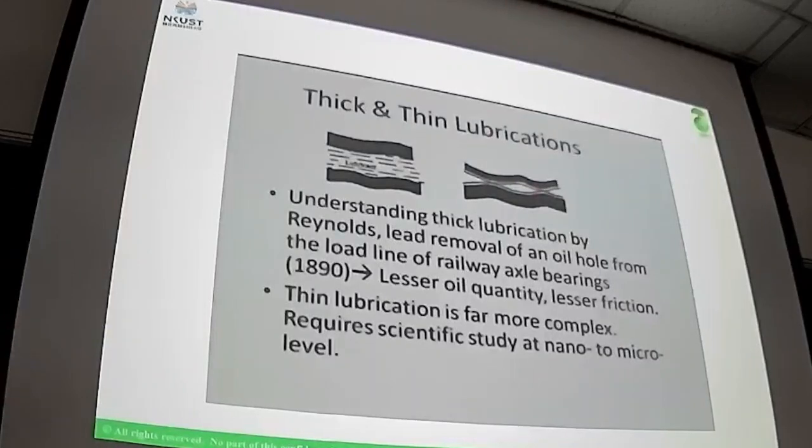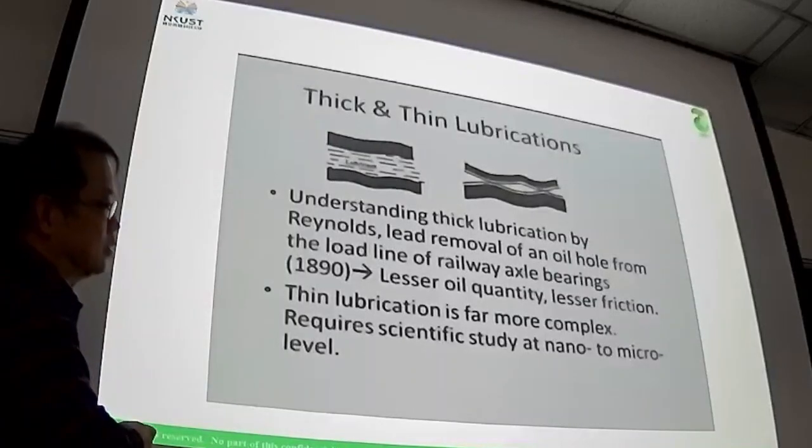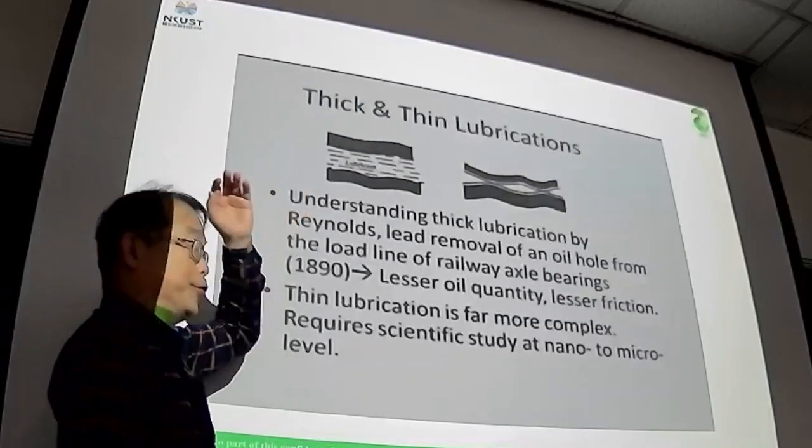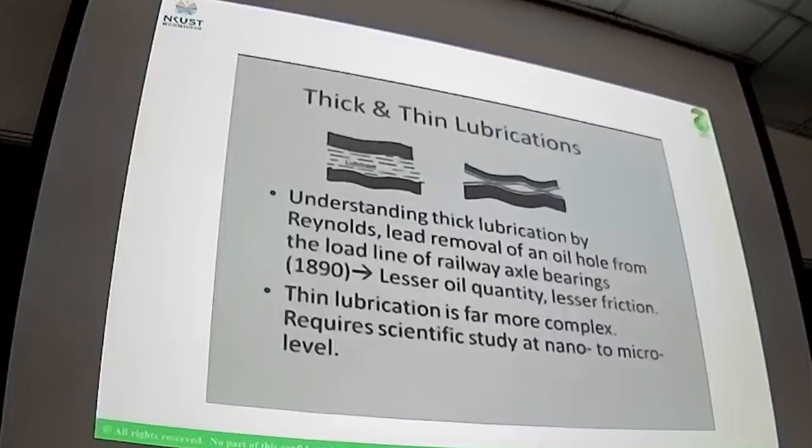Which means for thin lubrication, the coefficient of friction should be bigger than for thick lubrication, because for thick lubrication you don't have any physical contact. So usually it's only the fluid friction. So the coefficient of friction for thick lubrication tends to be small.